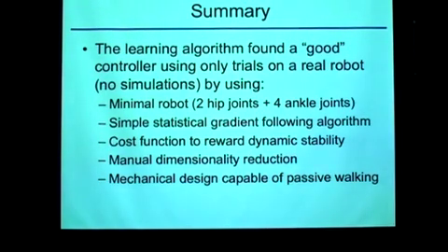I mean, the plane that I'll tell you about more on Thursday, our perching plane, which you've seen quickly, is one actuator, and depending on how you count the elevator, 8 degrees of freedom roughly, and it's 8 state variables, and it's just very, very hard to build a good model for that that's accurate for the long trajectory, all the way to the perch, such that LQR can just stabilize it. We're trying, but there's something sort of beautiful about these things that just work without building a perfect model. Okay.